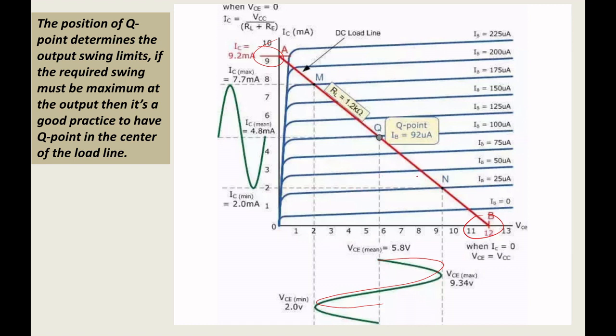But practically, the difficulty is, for example, if you take a common emitter circuit, you know the master equation for the output terminal current: IC equals beta times IB plus (1 plus beta) times ICO. You studied this equation in the previous semester. ICO is directly proportional to temperature changes.